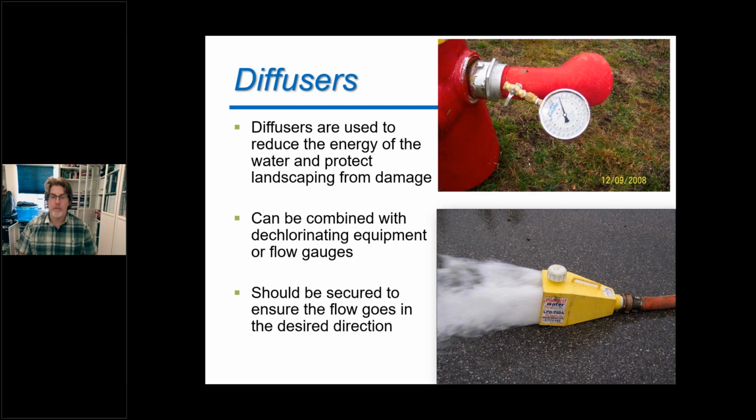of sitting out on the road on its own, we can make little contraptions where you can have a little side pedal off here. You can put your truck tire on there to hold it in place. They make them with a hitch mount, because what you don't want is, when you open that hydrant up full blast, that thing to start swinging around out in the roadway. So you need to make sure that they are secure.